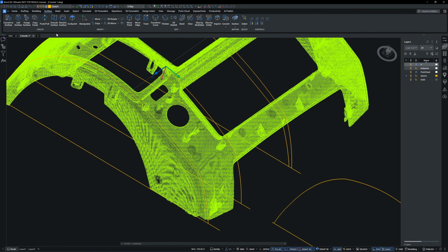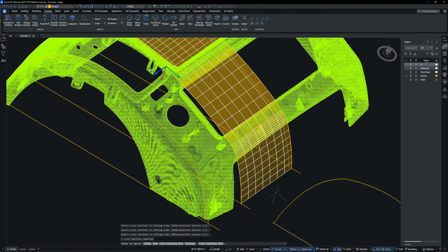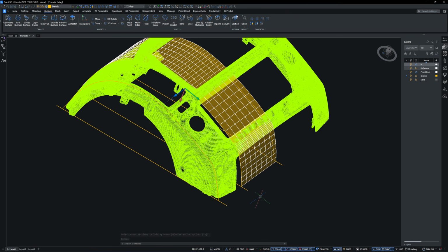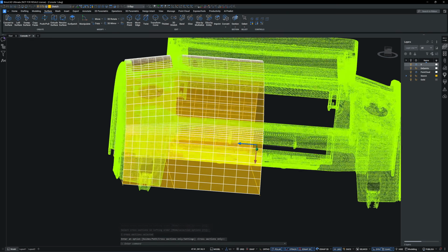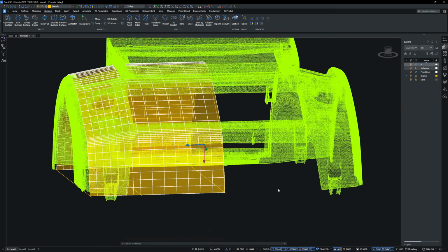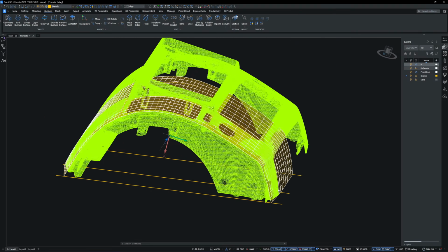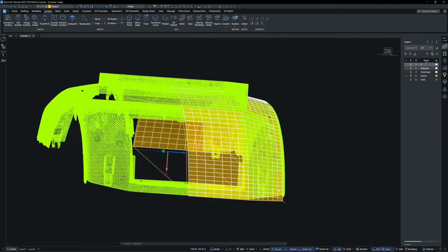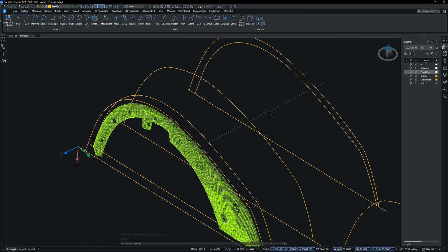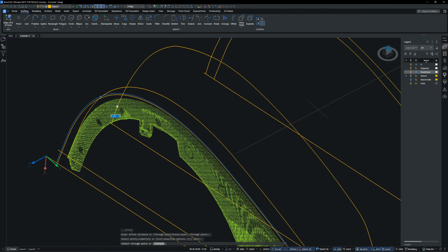I have positioned the cross-sectional sketches I traced. The two on the right share the same profile, while the one on the left is slightly smaller. You can create a lofted surface by selecting the two polyline sketches. Lofting one section at a time won't give you a smooth surface, and this is what I want for these two first sections. At this corner, a fillet won't work. The profile just doesn't match.